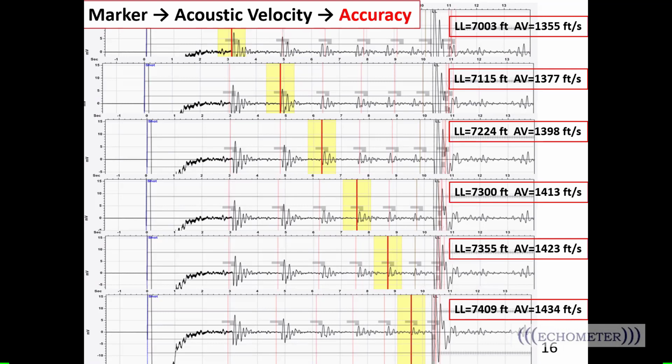So we would normally say in the past you can't see a leaky valve or a leaky check, because if you just shoot down one side of it, it's just going to show an echo, and it's not going to show a hole. It's just going to be a normal echo, like the valve is still intact. The only time you see something is if the valve's washed out or there's a hole, you'll see those, but you won't see a leaky check. So the dual shot method is what lets us see that, because the check will open and pass through the pressure wave from the shot.